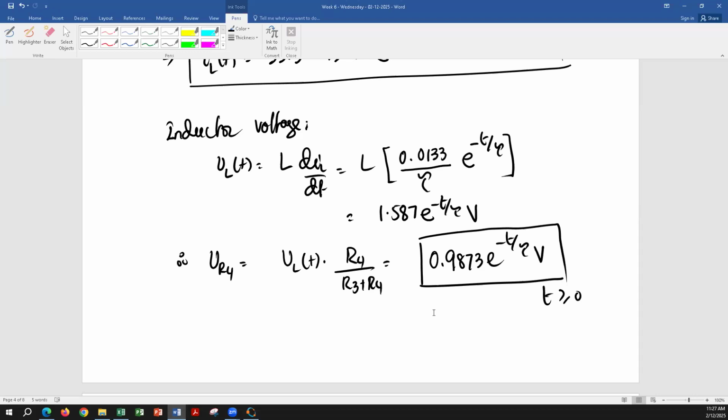All right, then what do we do? Right, but we have to find the time constant as well. So we find the time constant, or we find the value of A first, but the time constant doesn't do anything with the value of A. So the third thing that we do is we find the constant A in the equation by evaluating the equation at the initial condition. And then find the time constant. So these are 4 standard steps.